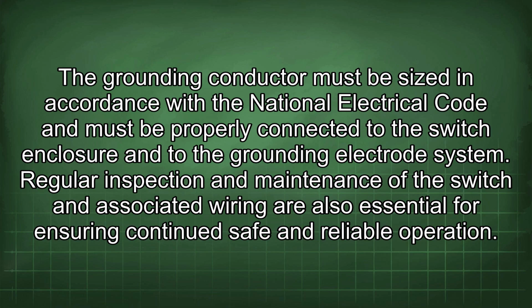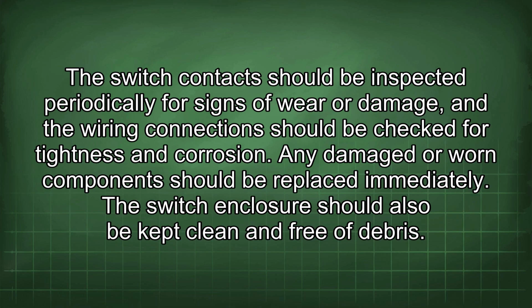Regular inspection and maintenance of the switch and associated wiring are also essential for ensuring continued safe and reliable operation. The switch contacts should be inspected periodically for signs of wear or damage, and the wiring connections should be checked for tightness and corrosion. Any damaged or worn components should be replaced immediately. The switch enclosure should also be kept clean and free of debris.